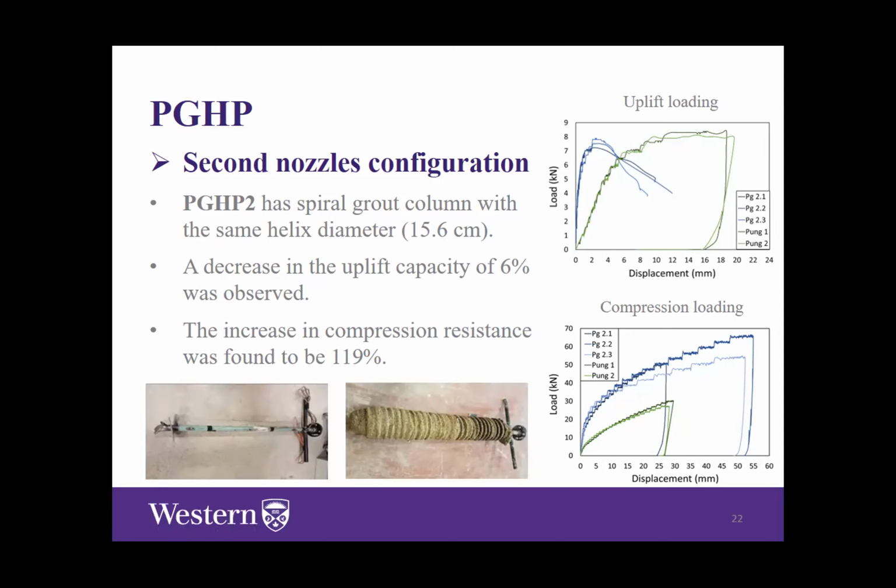The injected grout at the end of the installation will permeate through the voids of the supporting soil and provide a kind of cohesion. The injected grout acts as a glue which glues the soil particles together and provides additional cohesion to the supporting soil, which improves its end-bearing resistance.